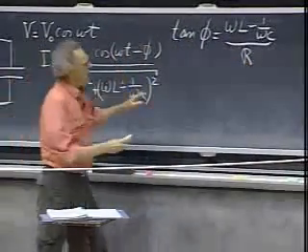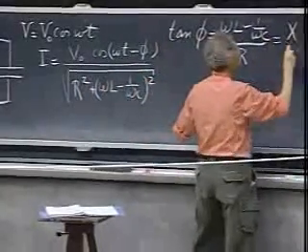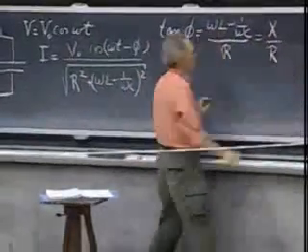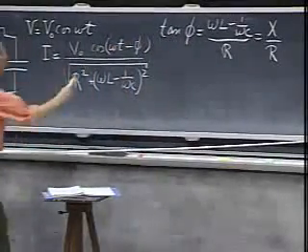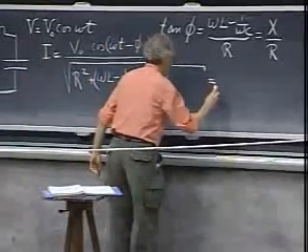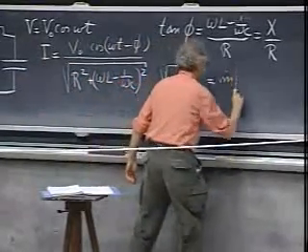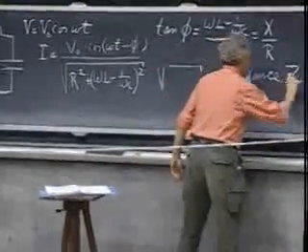We call this the reactance, the upstairs, for which we often give the symbol X, and so this is also X, then divided by R. And this whole square root that we have here, we call that the impedance. The units are ohms, and we call that Z.